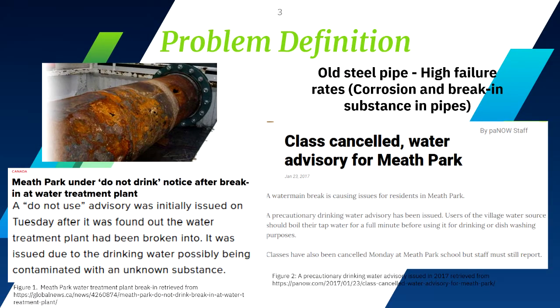The problem has arisen in the village of Meath Park in the late 21st century, which was caused by the water distribution system shown in figures 1 and 2. By the information provided by the Water Security Agency and the newsletters from Meath Park, our group identifies it was caused by the aging of metal pipes. When pipes get old, they cause corrosion. Then the pipe loses its strength and becomes fatigued, causing cracks in pipes. Additionally, it will reduce bond strength, reduce shear capacity, and limit ductility. Overall, all of those problems will increase maintenance costs, and it may cost more money than replacing them with new ones.